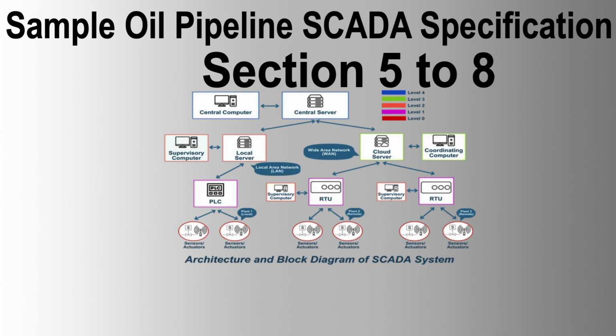8.2 Integration with SCADA. 8.2.1 Operator Interface. Daily pipeline operator interactions with the application software shall be performed via the SCADA System Man-Machine Interface, MMI, and operator workstations. Reconfiguration of system parameters shall be performed by a system engineer via the SCADA MMI.